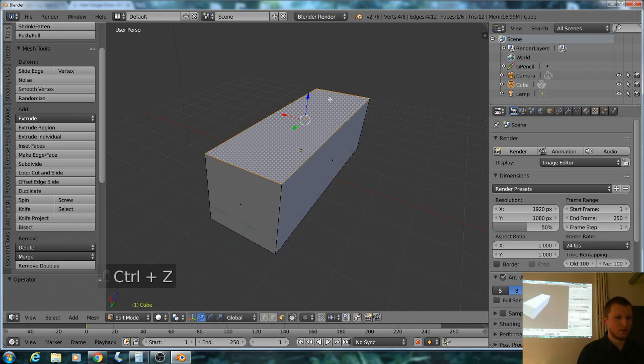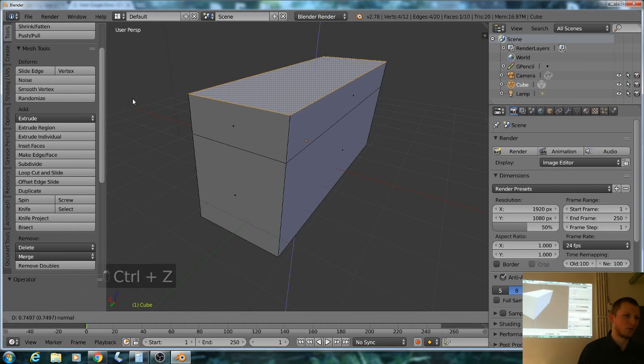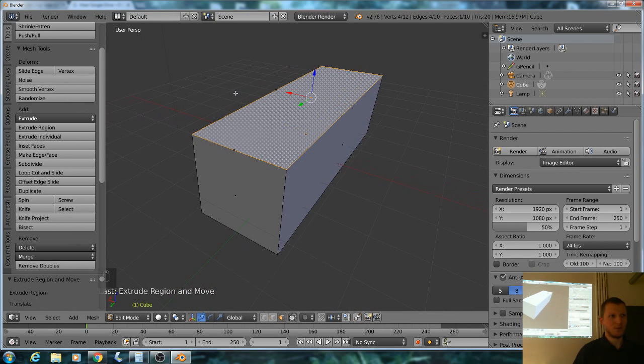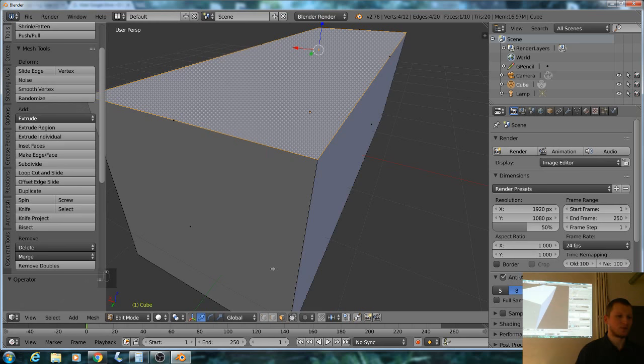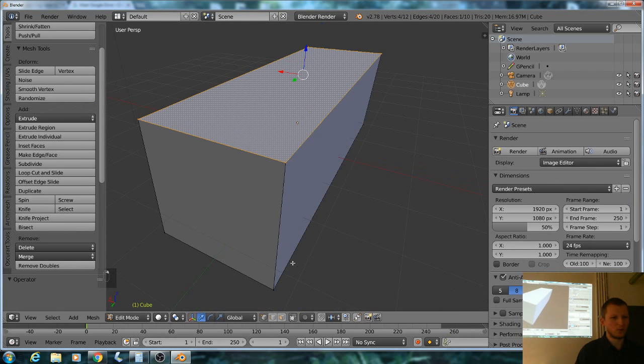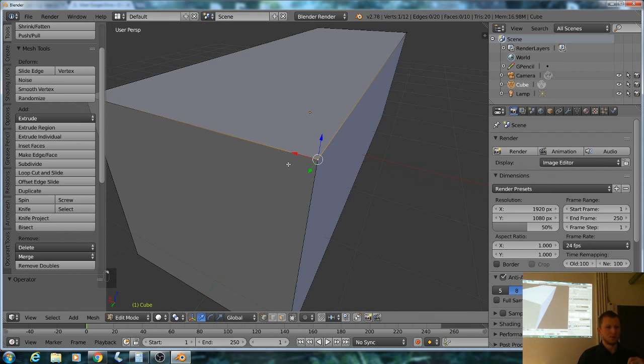So basically, if you start your extrusion and halfway through you decide that you didn't actually want to extrude it and you press the right button, then you should definitely also undo the command by pressing Ctrl Z. If you don't undo the command, it's a little difficult to imagine in real world terms, but currently you can't really see it, but exactly in the same place there are two vertices and two edges and like three faces, I guess.